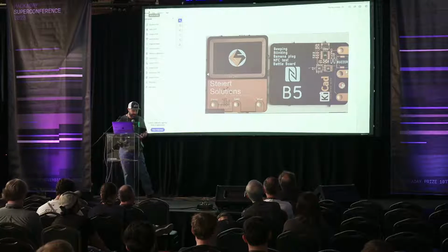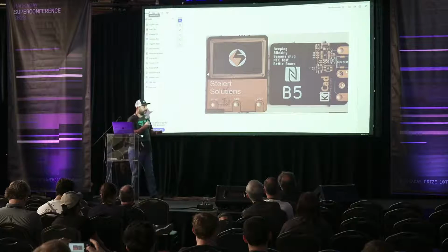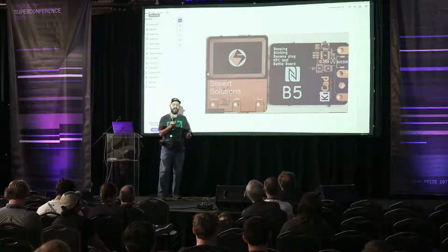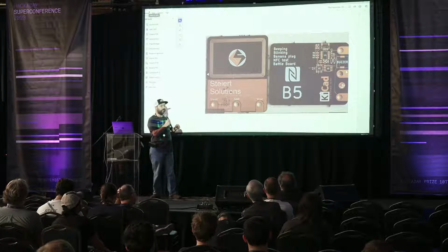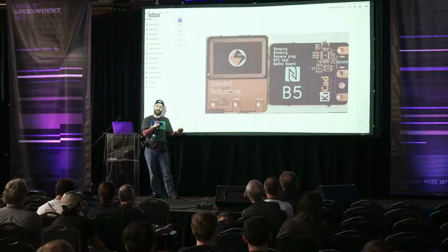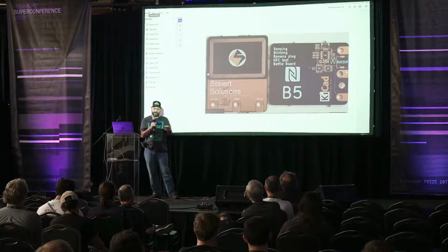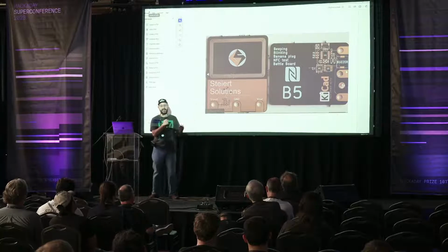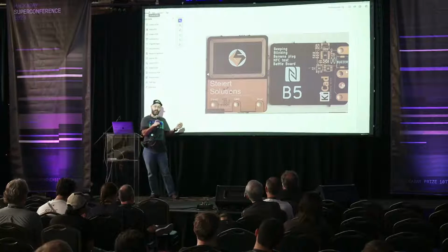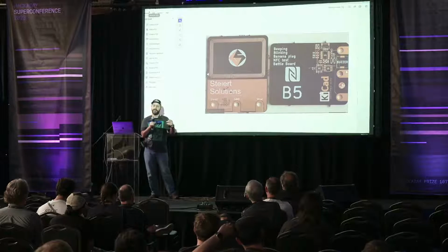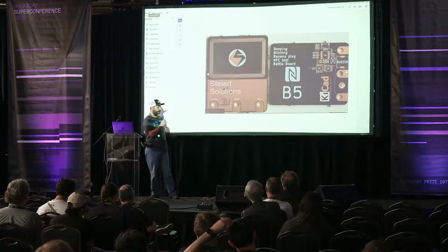But I do have, I'm working on another iteration. The NXP micro is not the easiest thing to program, and to make it a little more accessible, I think I'm going to go back to an EEPROM with the power output, and I'm working with one of those 10-cent WCH micros. So I'm going to try to do that so you can program the WCH micro to do some stuff, or I can put a golden image in the WCH micro, because actually the NFC tags, you can program them from your phone. So you don't need a programmer or anything, and if I preload the micro with some interesting code that reads the EEPROM, then people can customize it without programming it.